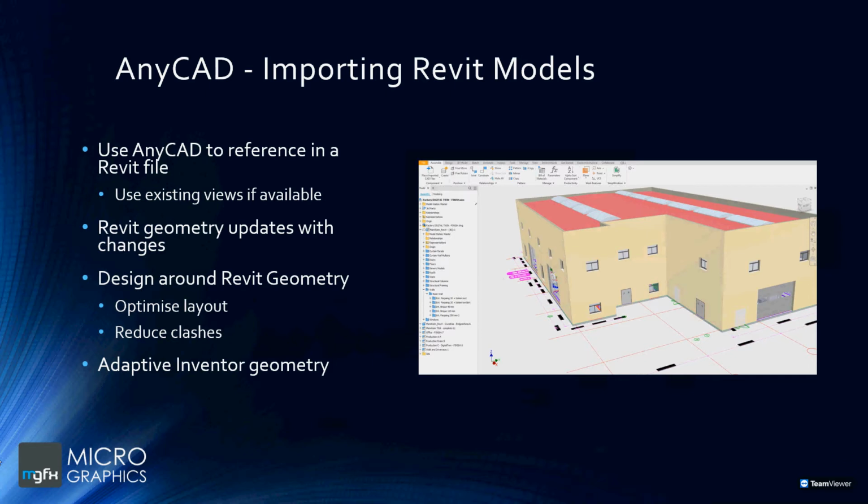Once that model's ready, the Inventor user can then import that Revit model into the design as a referenced file. So using that AnyCAD import feature, they can reference the file in. This means there's a live link between the Inventor assembly that is created and the Revit file. The changes in the Revit file are picked up and updated inside of Inventor without needing to re-import that Revit file. This affords the designer the opportunity to design and place their machinery around the existing Revit geometry and avoid potential clashes within the design.